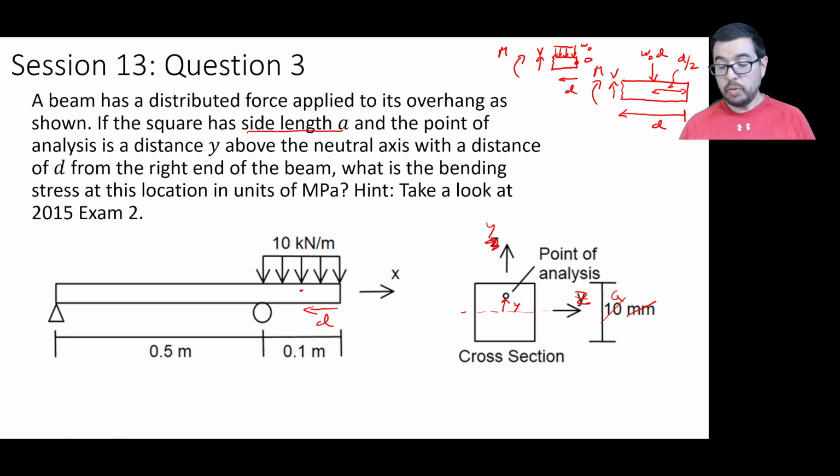So to do that, we perform equilibrium. We're not going to use the differential integral forms here. We're just going to calculate the equilibrium. So the summation of the forces in the y direction is going to be equal to 0. And we have a V that's acting positively, as we said prior, and we have our minus W naught D, and that's going to be equal to 0. So now V is just going to be equal to W naught D.